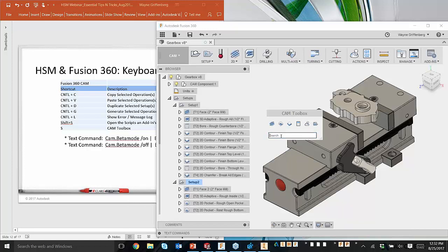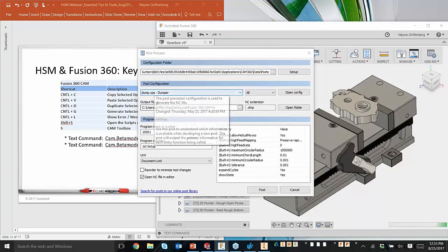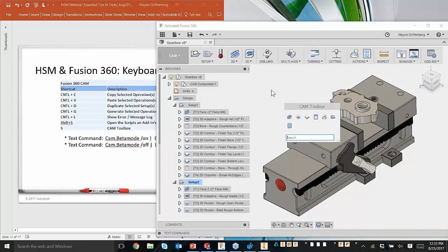Now, if I wanted to do something like this, let's say I want to post right from that box as well. Now, if I hover down here, you see that little arrow. I can click that arrow and it puts it on the quick toolbox. So now I have this CAM toolbox that has the post-process on it. So now if I hit the S key, I can just go right to post-process, and I can post-process whatever I had highlighted. We'll talk about this later. But I can quickly get to post-process just by simply hitting the S key, post. So you can add any function you want to that CAM toolbox that you search for. And you can add it in, and it's a really quick, easy way to work to get there. We'll talk about more of those functions in a little bit.